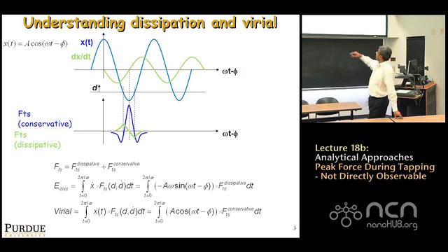If that happens, those forces will be something like what's shown in green. Why? Because they will depend on the direction of the velocity. So you see, if you look up at the green curve on the top, the velocity is changing directions. You see that? At the bottom, the velocity changes directions. Therefore, if you have a dissipative interaction force, it must also change directions because it depends on velocity.